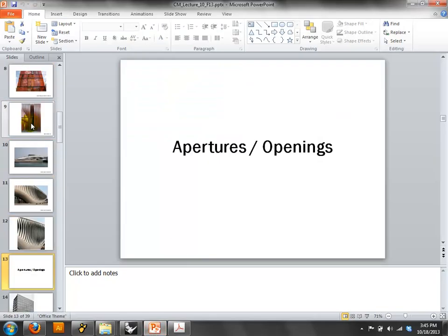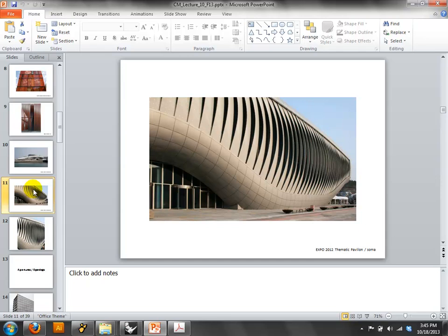It's a very good way to do it. So the idea of this is to look at the angle between the louver and the sun and to decide how open we want it, how closed we want it. Ostensibly, when the sun is directly perpendicular to that, we want that thing closed. And as the sun moves away, we want to begin to open it to let in indirect light.